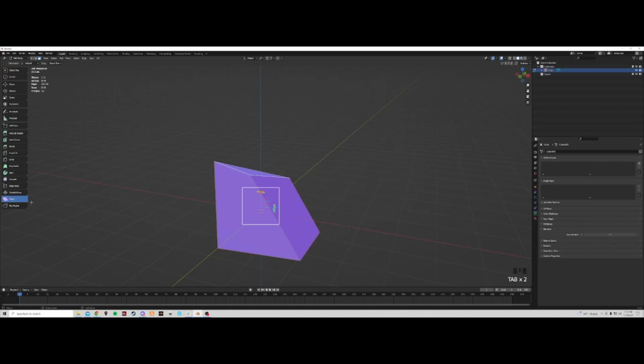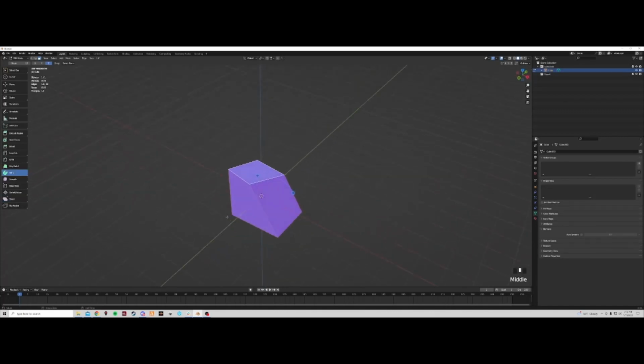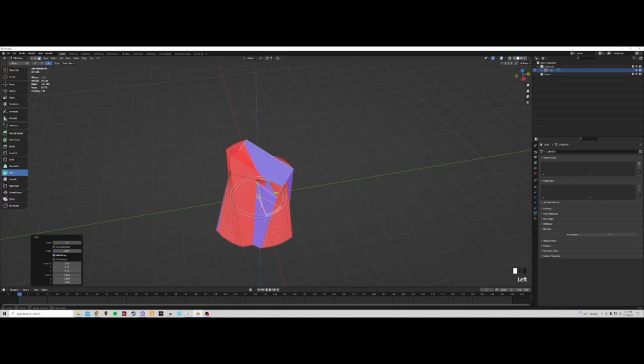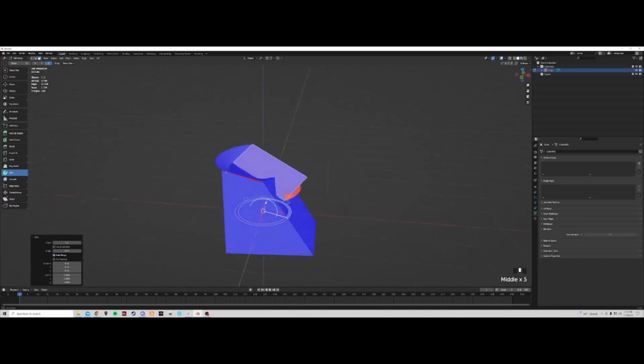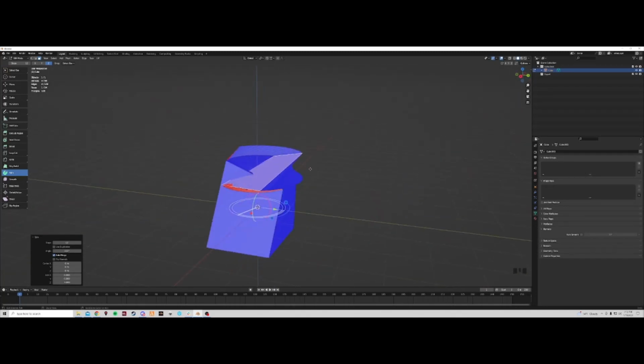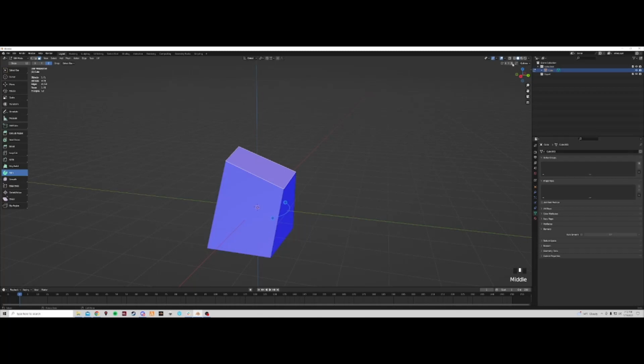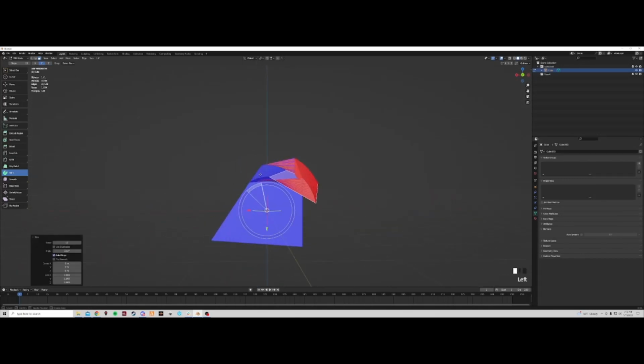Now there's also this spin tool, which is a weird tool. Okay, you can spin right now. If I use this blue one, it's going to spin on the z-axis only. And it's going to spin whatever I have selected. This face right here, if I have this face selected. It's kind of like extruding, but it extrudes and rotates at the same time, so it creates a lot of faces. Now I can do, let's say, the Y. Here we go. There's the tools for it. I want the Y-axis instead of Z. And it's currently going from the 3D first.